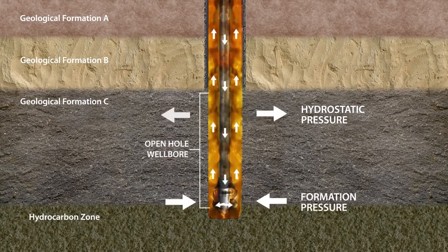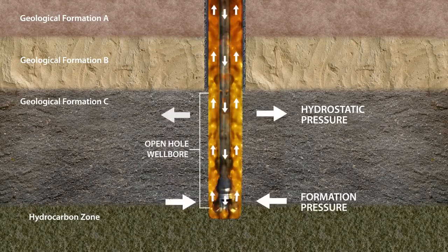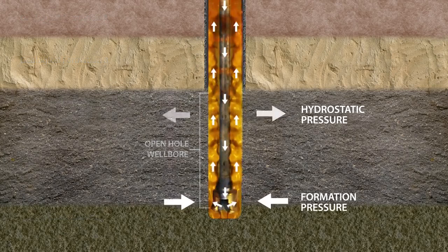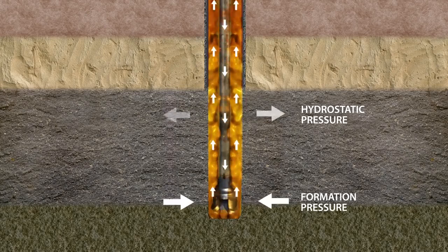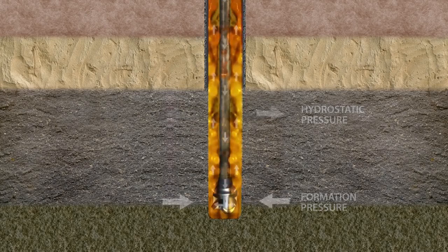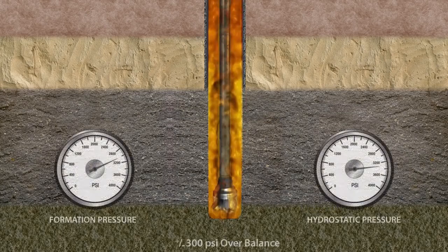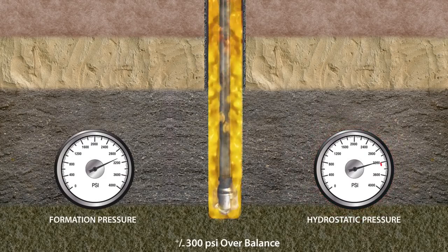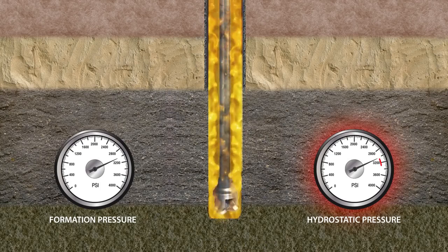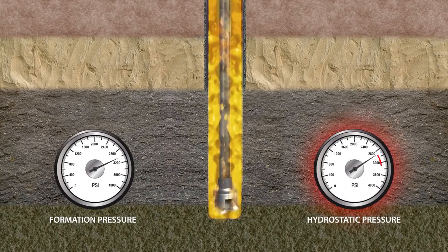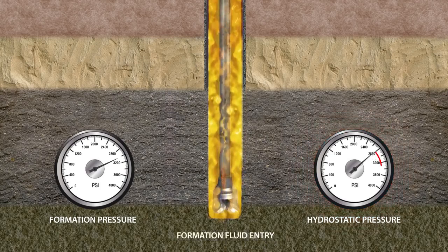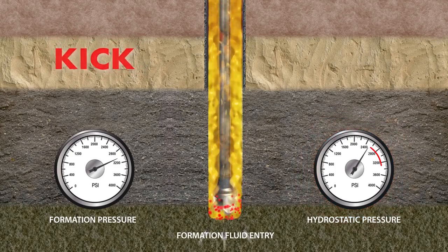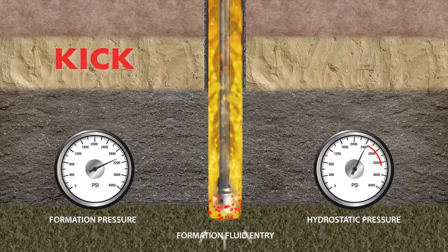This column must be monitored and maintained during drilling and tripping to prevent formation fluids from entering into the wellbore. During drilling, if the fluid column is not maintained with adequate mud density, making the formation pressure more than the hydrostatic pressure, formation fluids will find a way into the wellbore and a kick will occur. In this case, the well must be secured and killed.